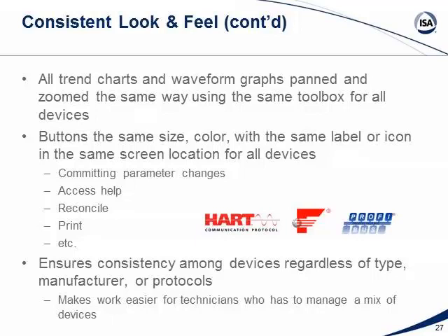So that if you take a DD from one device manufacturer and display it, and then you have a different device manufacturer's product, maybe it's another valve or pressure transmitter, and you pop that screen up there, that same Windows control is going to look exactly the same. And so it really provides a much more unified integration of all these different things. You don't have to learn each individual driver package for these particular devices. The consistency really makes it easier from a training aspect, because the way you interact with one device vendor's product is going to have that same look and feel as interacting with another device vendor's product.